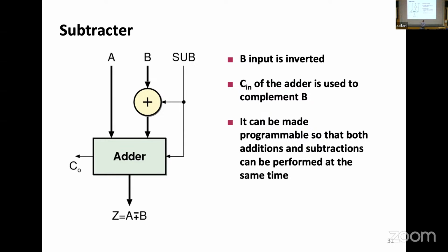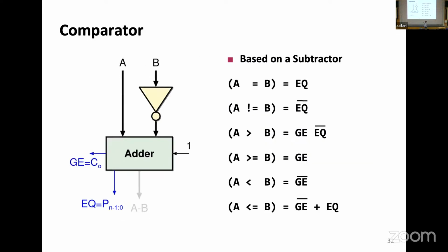If A is greater than B, the subtraction will be positive. So the number will have it on its most significant bit as 0. If A is smaller than B, the subtraction will be negative, meaning that the most significant bit will be 1. And you can look at it now. There are some strange things here, so please ignore them. But just trust me that the heart of the adder, or the heart of a subtractor, it's an adder, you make it a subtractor, and by comparing these two things with very little additional effort, these things, whatever they are, I'm not discussing them at the moment, are already inside the adder.